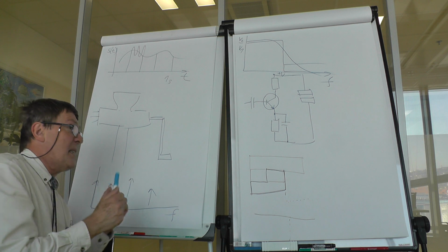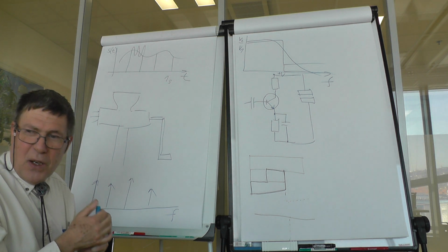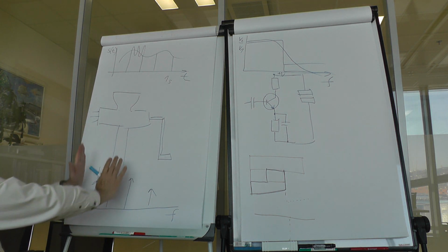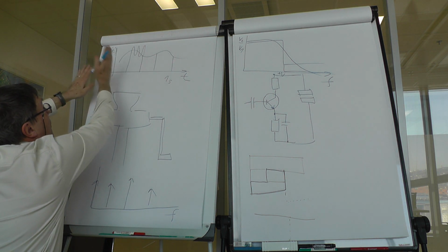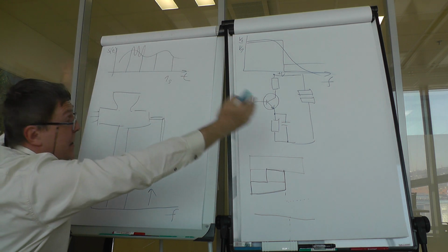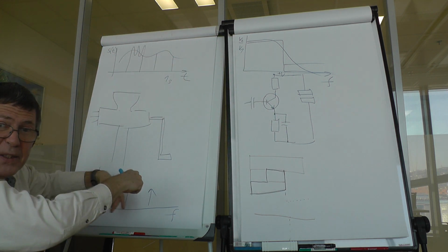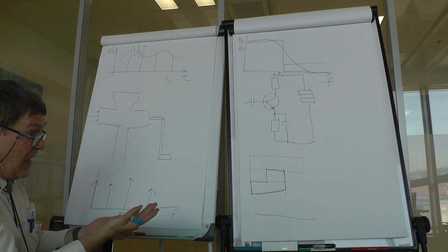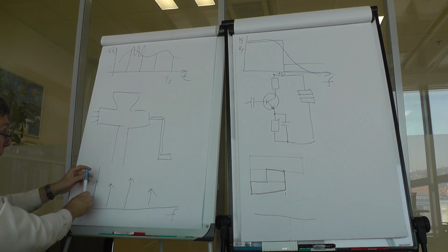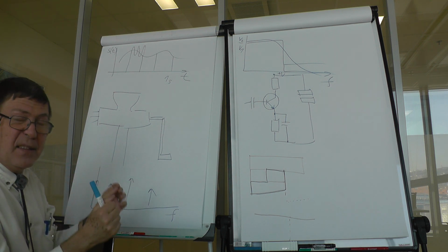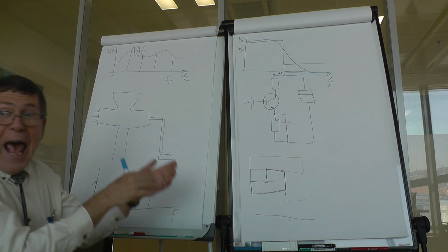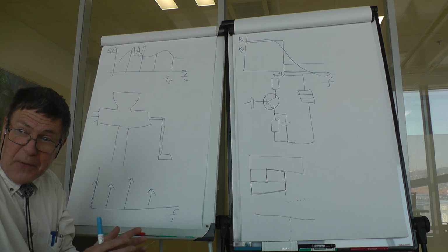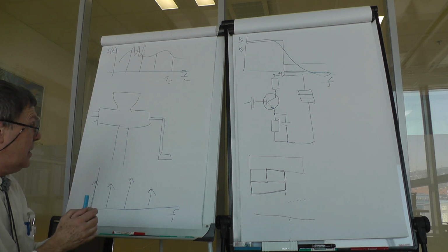Then there is a second property which is also important. So again, we have a set of samples in the time domain. We apply a fast Fourier transform. We carry that out. We get out a set of complex numbers that describe magnitudes and phases of the respective frequency components.